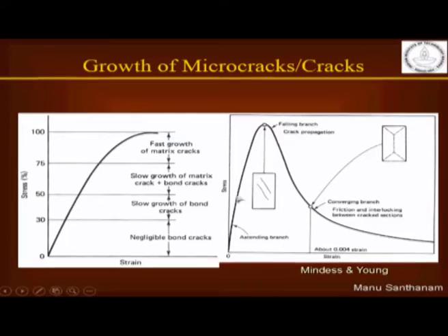So, if you look at this, the stress versus strain relationship for concrete truly actually looks like this. You have this increasing stress region, you will go to the ultimate stress, and then what you start seeing is that with increasing levels of strain, your stress actually starts falling. That means your material is undergoing what we call strain softening. Now, this is something quite opposite to what you might have heard about in steel, where we talked about strain hardening behavior that occurs after the plastic flow has happened in your mild steel, right.